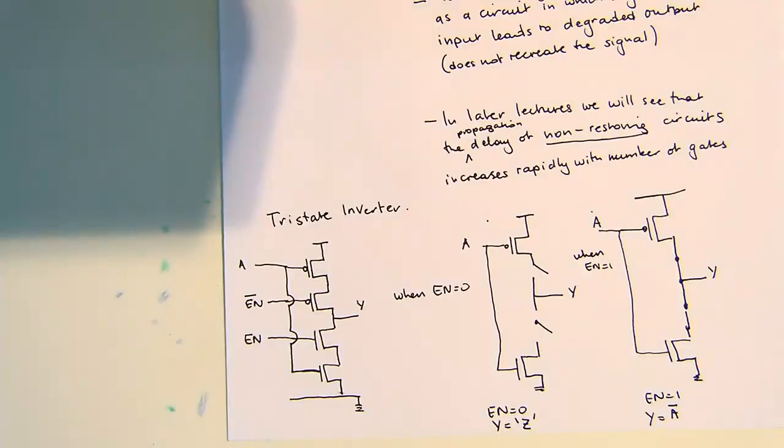But essentially, the reason why we want restoring circuits is they remove noise, they get our signal back, but also what we'll show in the future is that if you've got non-restoring circuits, they also increase the propagation delay through that system. So essentially what you want to do in many cases is occasionally put restoring circuits between the various outputs in order to clean up the signal and also reduce your propagation delay in combinatorial logic. Right? One of the other tricks that you can do is use sequential logic or synchronous logic, and that you're gating and then converting, and that helps you, right?